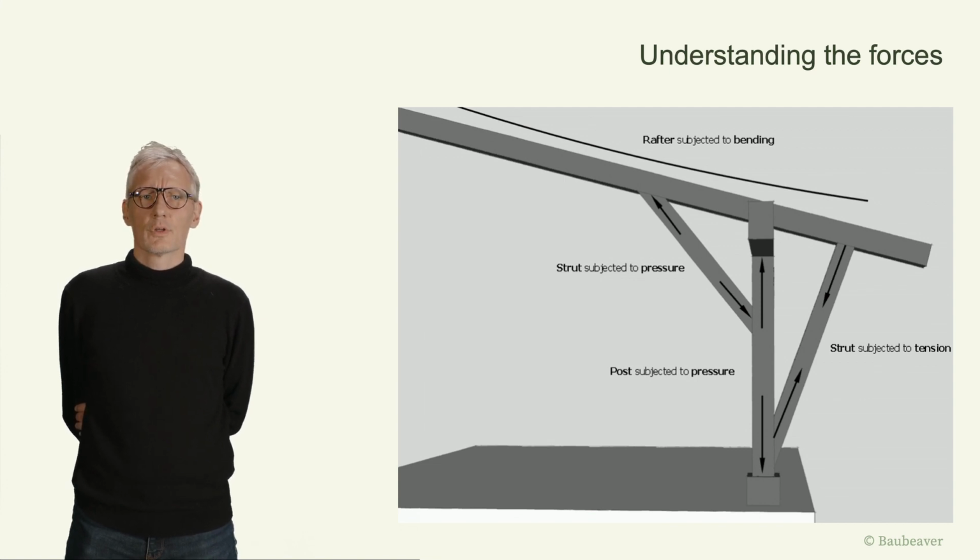In many real-world applications, a joint may experience a combination of these forces. For instance, in a timber-framed building subjected to wind loads, the joints might face both tension and shear. Therefore, understanding the complex interplay of these forces is critical for choosing the right joint type.